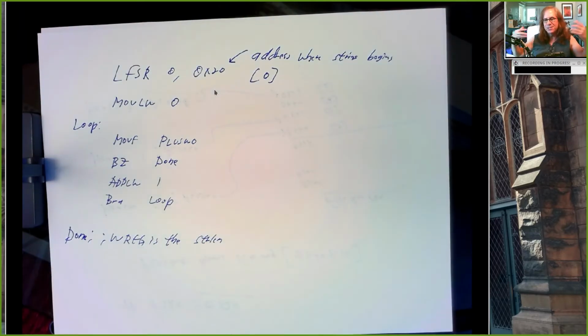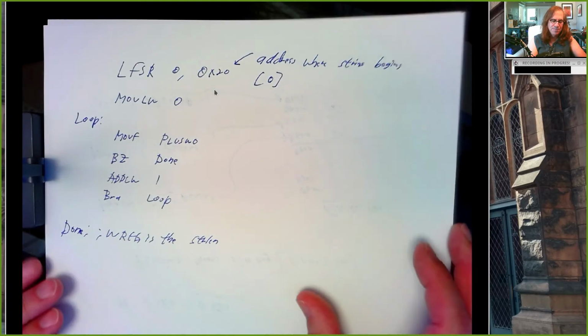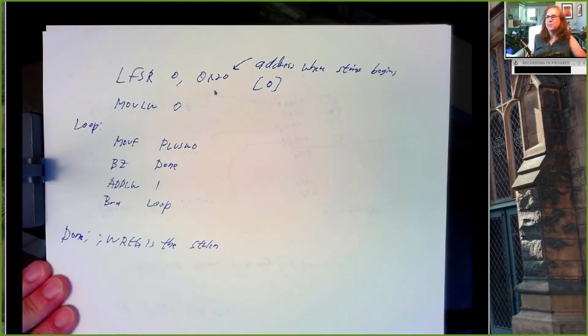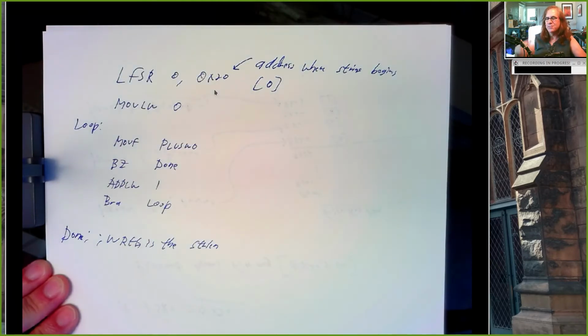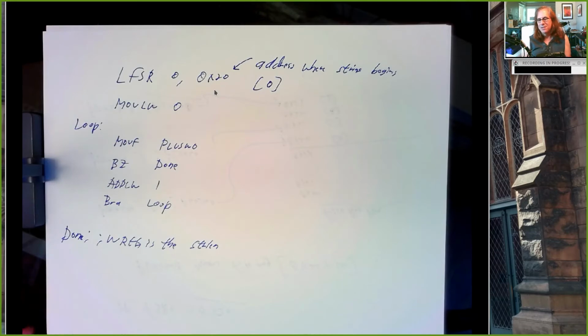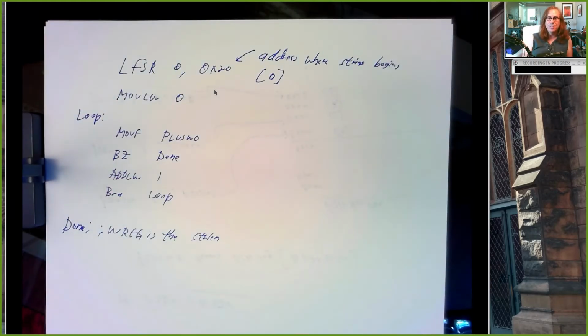But if I was going to start at some arbitrary location, I could put this into a function where you set the W register equal to the location of your first character, and then do all of this. And when you return from here, W register has a string length. And we've got our first C library function written. So these are useful for moving through an array.